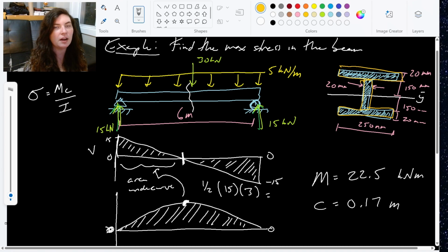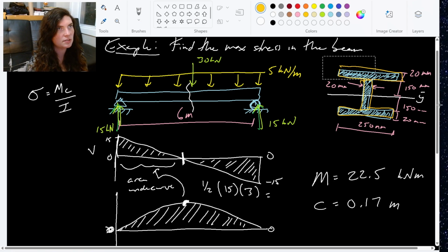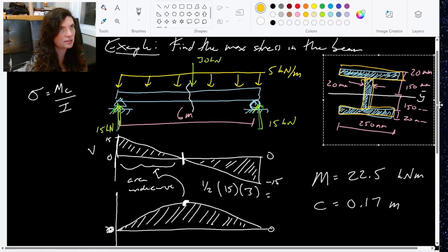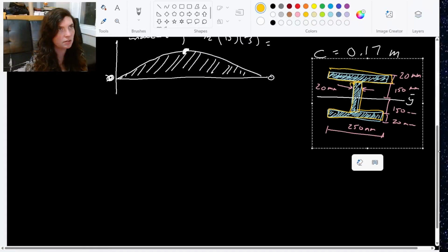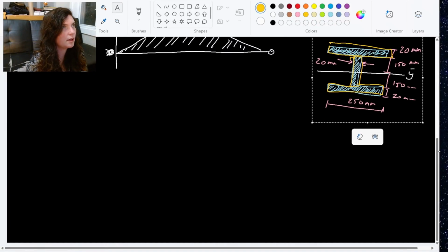And then I use that parallel axis theorem, that A times d squared, to offset it, and I sum everything together for each individual part. So for me, I like to use the table version when I'm calculating this. I'm going to move this down for reference, but I like to use a table.